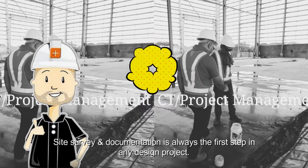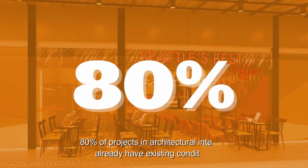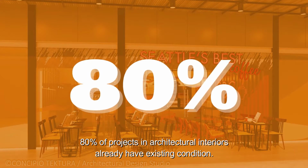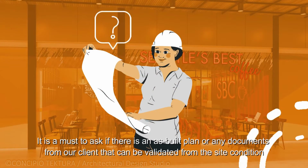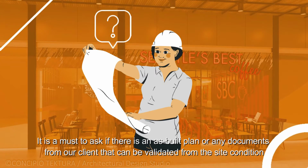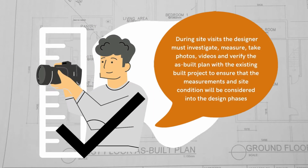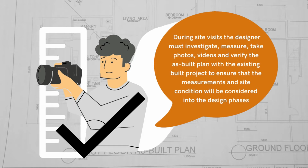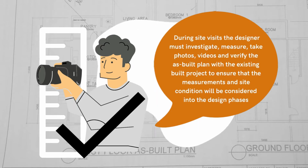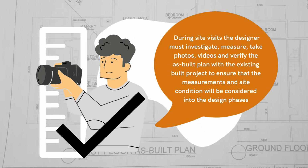Site survey and documentation is always the first step in any design project. 80% of projects in architectural interiors already have existing conditions. It is a must to ask if there is an as-built plan or any documents from our client that can be validated from the site condition. During site visits, the designer must investigate, measure, take photos, videos, and verify the as-built plan with the existing built project to ensure that the measurements and site condition will be considered in the design phases.